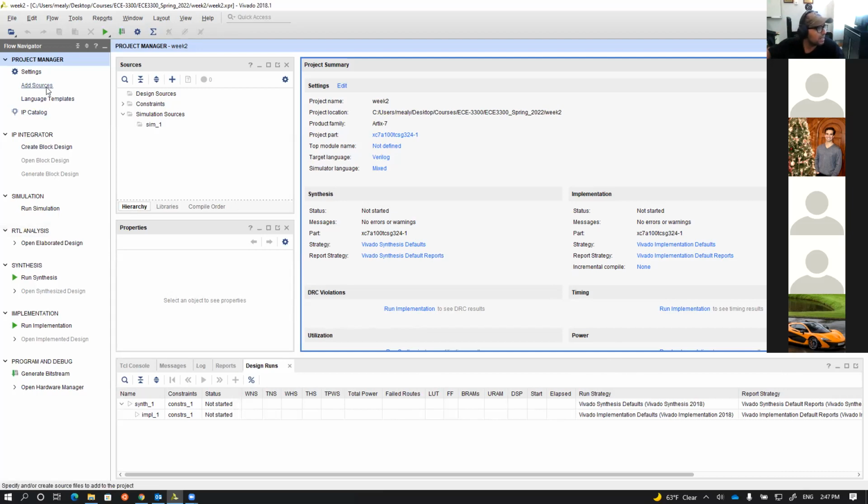Anyway, now we're going to start our project. If you guys remember, we said that in the language you have to have module, and then you have to have end module, and from there you can define input and output ports, right? And there you can start defining the types of data that will help you to write the code. And we said there are different types of approaches for implementing any algorithm or any piece in Verilog. We said we can use gate level, or we can use structural modeling, or data flow modeling, or behavioral modeling. Do you guys remember that? Yes. So we're going to start slowly, right? Which is gate level.